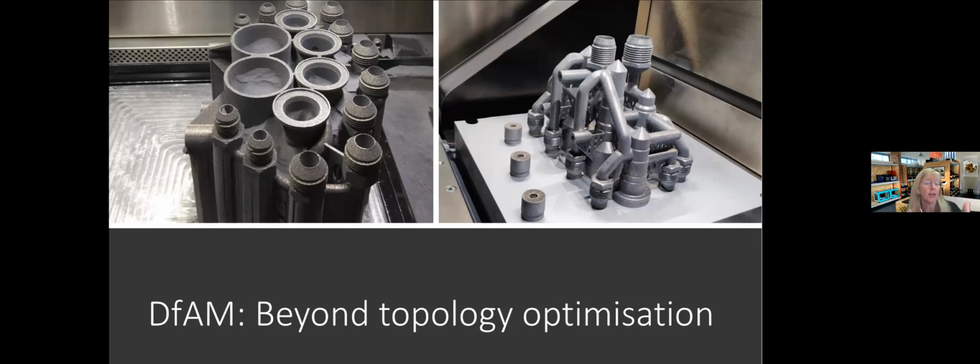And like in this example, the idea of incorporating support structures into the part itself and the design detailing in here to reduce the need for support structure is, I'd say, a really good example of practice. And anybody who's had hands-on experience with metal printing and removing support structure afterwards will know how critical even reducing any support structure that has to be removed after printing really is.